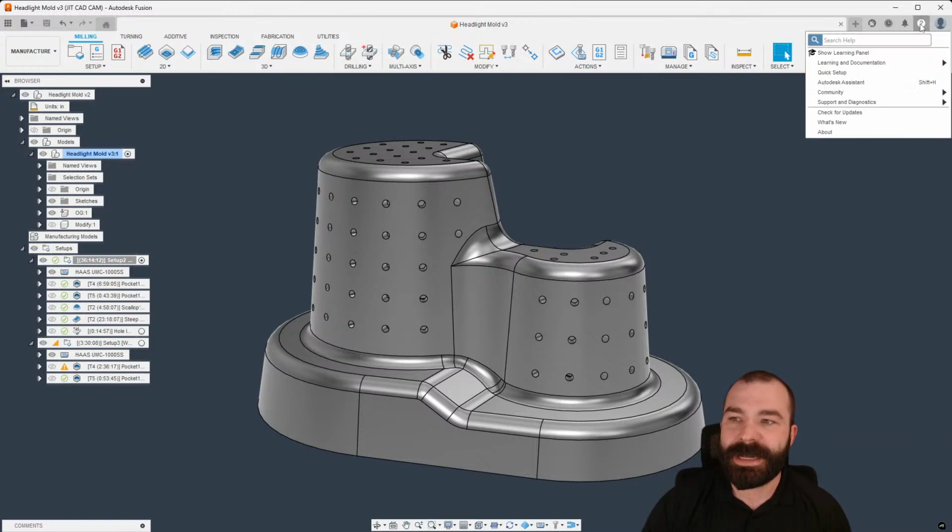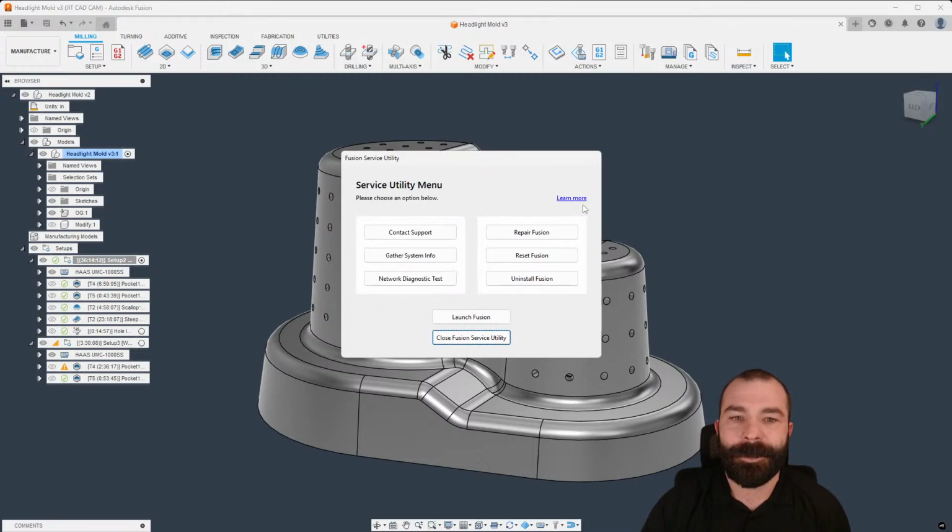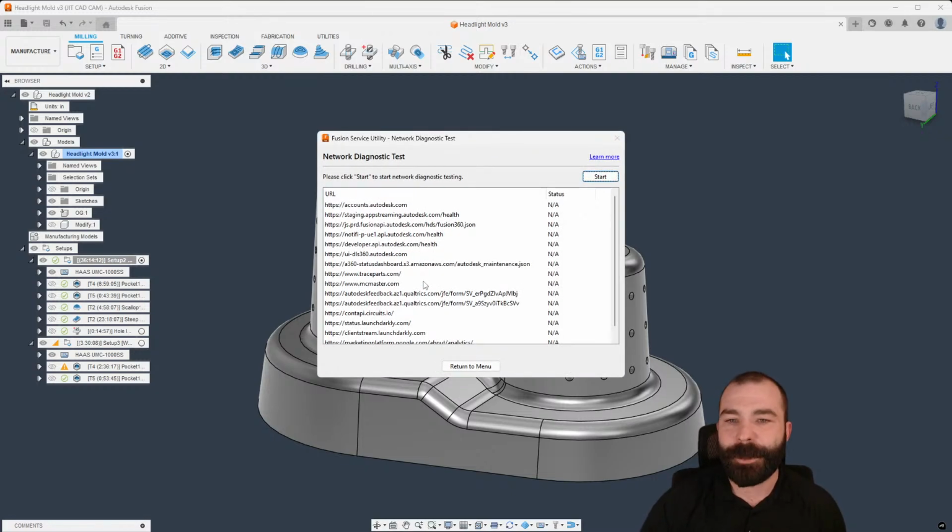So the next thing we tend to have people run when we talk to them at JIT CAM is the ability to set up the service utility menu on your end, right? Now, this is the reason why I like making this video, because I'm going to send this video to a lot of you. If you're having network diagnostic problems, what is happening is your Fusion is disconnecting and reconnecting a bunch. Maybe your tool libraries and your machine libraries from the cloud are loading very terribly. Well, we can run a network test.